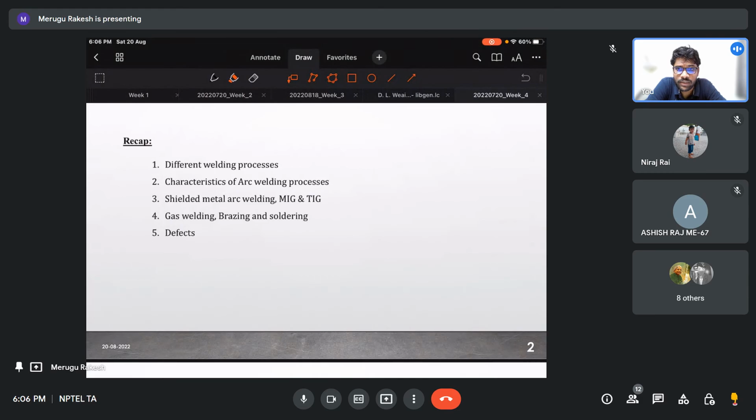finally it ended with defects in welding, such as slag inclusions, insufficient filling, pipe defect, and penetration defect. The main things to avoid these are to keep the welding surface clean, preheat the surfaces, and use the correct combination of electrode and flux material according to the weld joint. You can also use some shielding so that oxides and gas entrapment in the weld pool are reduced.